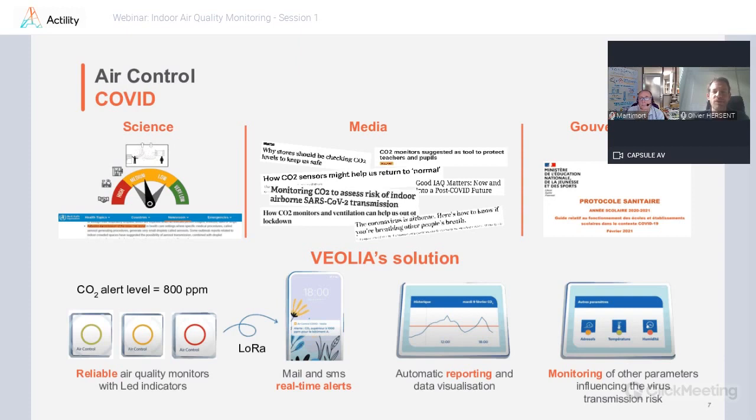You just need to do site surveys from time to time, or even just take into account feedback from users. In the packet error rate statistics, this is the most important thing to measure: the packet error rate of a sensor. If it's high, you get lots of errors. You need to reinforce the network locally, and you can do so with very inexpensive picocells. I don't have one around, but they're very small boxes like a Wi-Fi relay, and that allows you to reinforce coverage in this area.